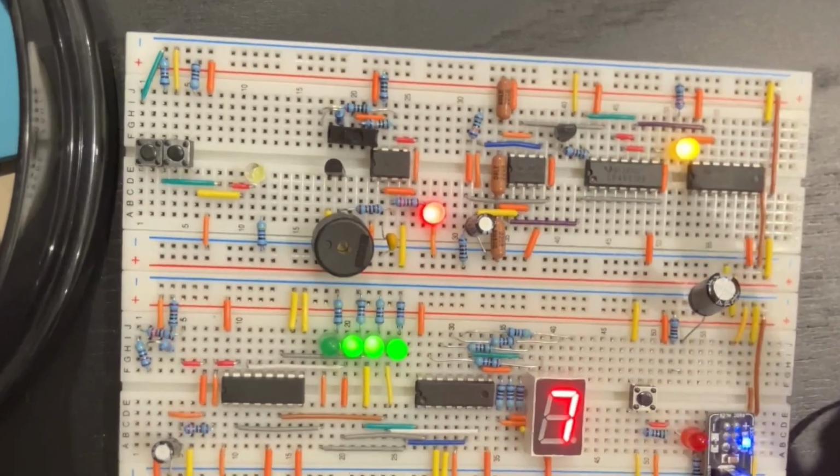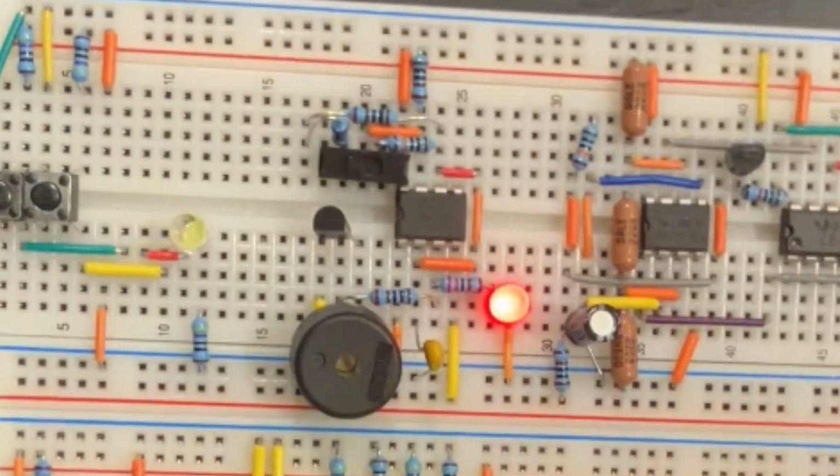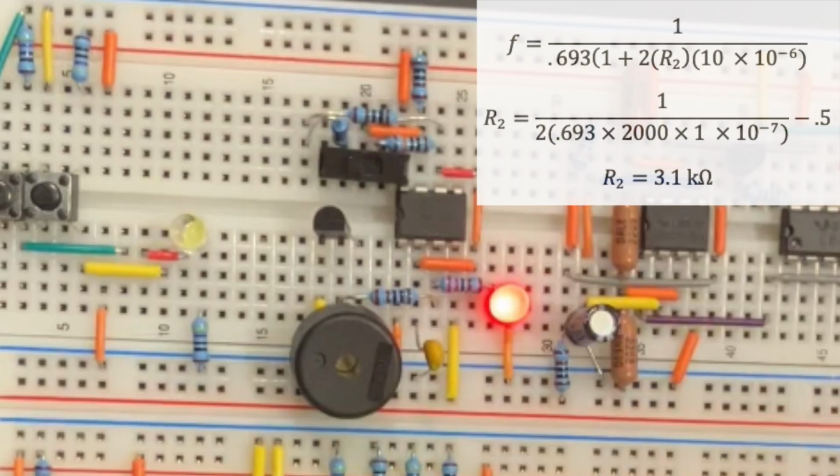Here's our 555 tone generator. I've changed the resistance and capacitor values from the original oscillator to create a square wave frequency of 2 kHz to power our piezoelectric buzzer. The math is shown on screen.